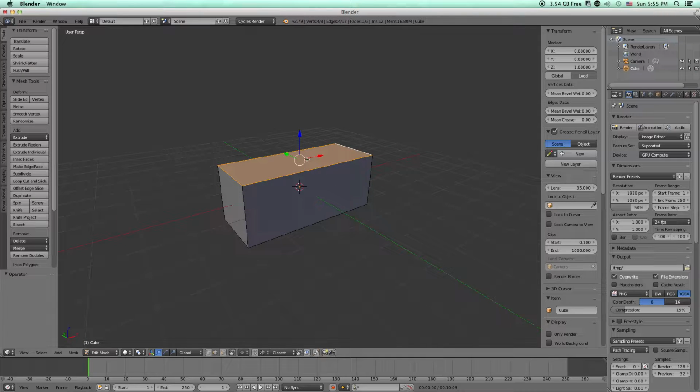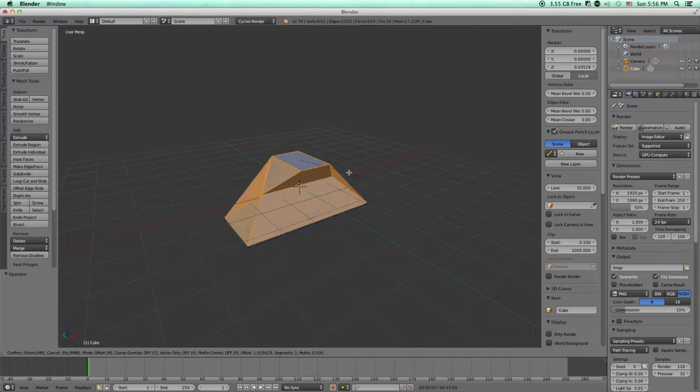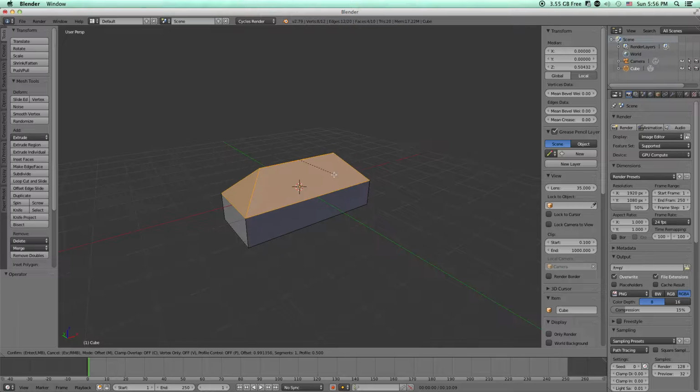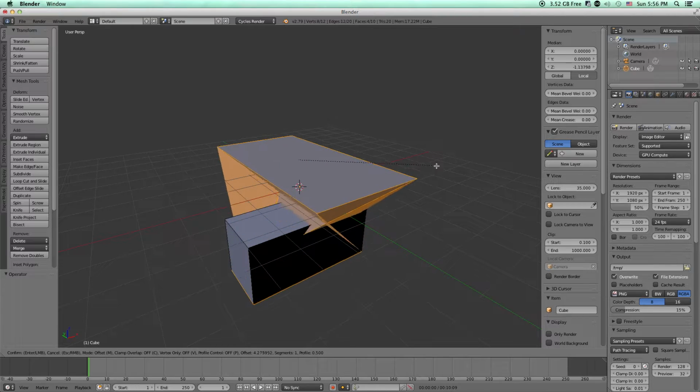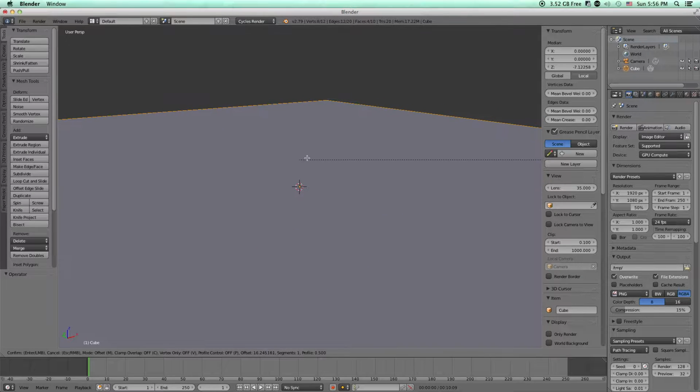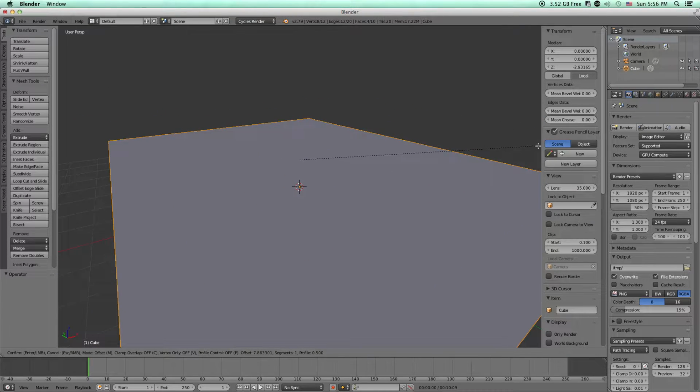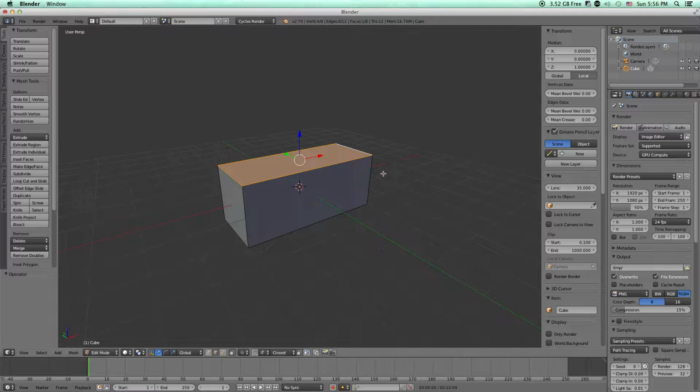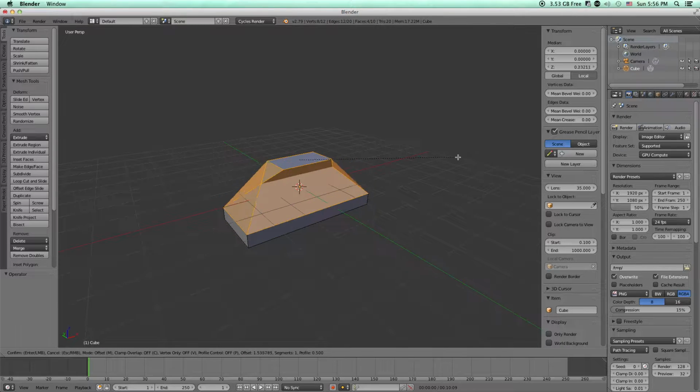And you can undo, and be sure whenever you use something like the bevel tool, which is Control B, that it's always going to be from the center of whatever you've selected, that it's going to pull away from that. So if you end up something really crazy looking like this, then you can click out of it, move your mouse away from the center here, Control B, and then it will be a little easier to handle.